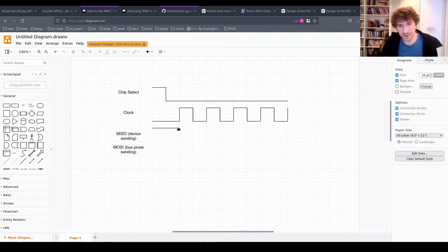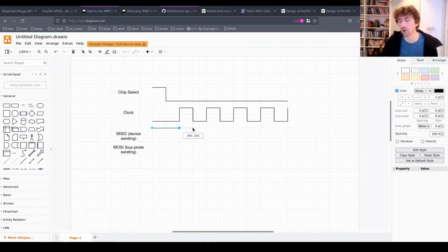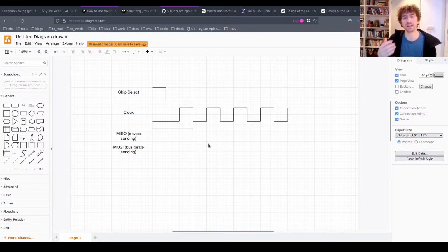So most of the time, I'm trying to remember, you can configure all of this stuff in SPI, but most of the time, or the default setting, the data is captured when the clock goes from high to low, and then it's actually captured in the middle of the clock, and that's on both the sender and the receiver.